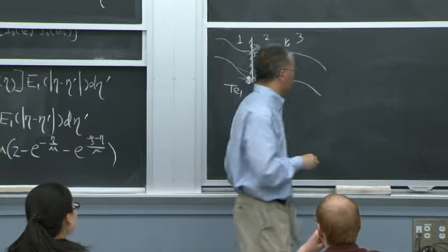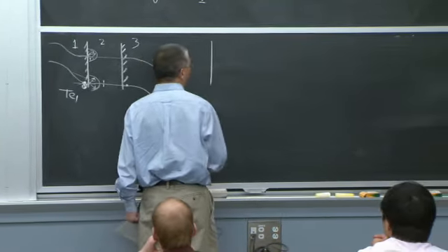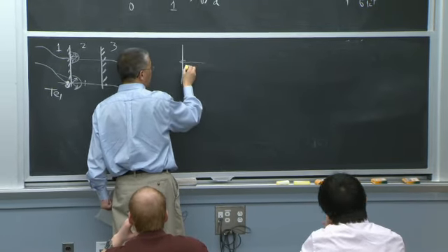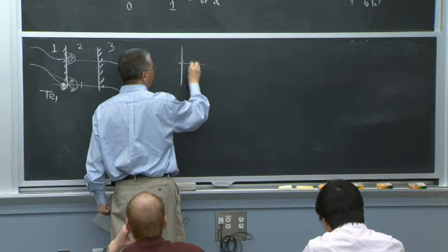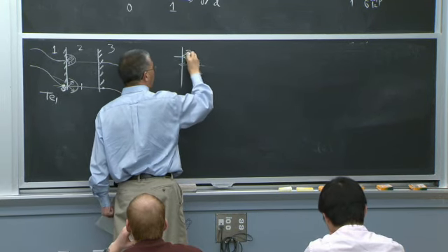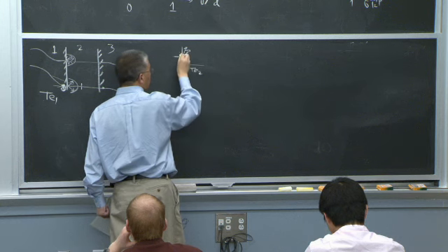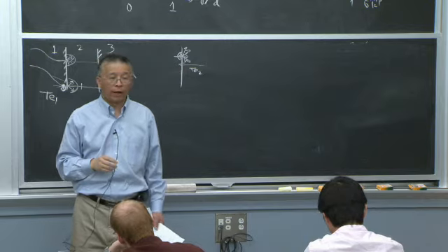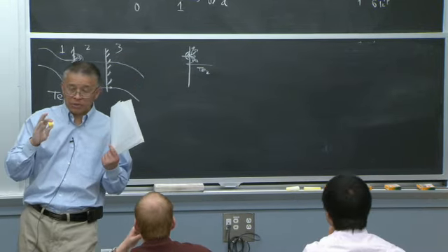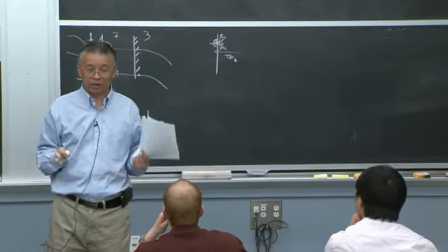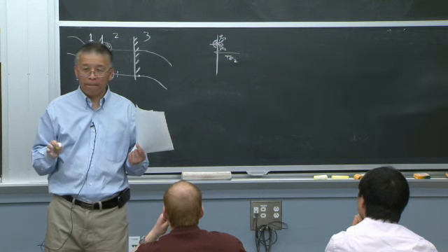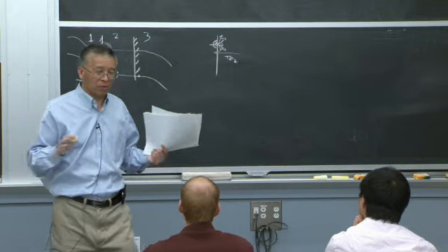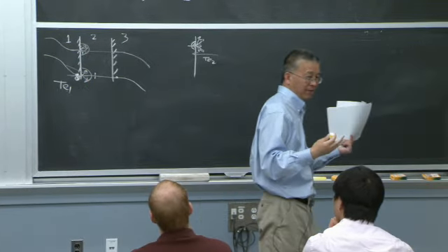What happens is that this is the interface I discussed before, right? If you look at what comes to this side, it is TE2, and TE1 is going out like this, but the TE2 goes out like this because it's a lower temperature, right? So if you define temperature consistently, you should not have that jump. This is a highly non-equilibrium situation. There's no good temperature definition.